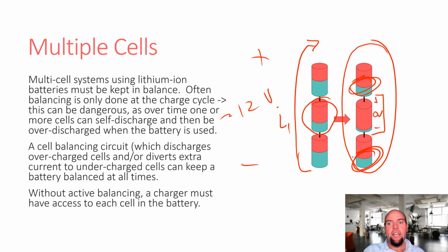But the bigger problem is if you keep running this battery, you will actually reverse charge it. It'll be fully discharged, and these other batteries will keep forcing current to flow through it, and that really destroys a battery. So whenever we're using lithium batteries connected in series, we need to make sure they are balanced. Balancing is a way of maintaining the same level of charge, or usually the same level of voltage, across every single battery in a series collection of batteries.